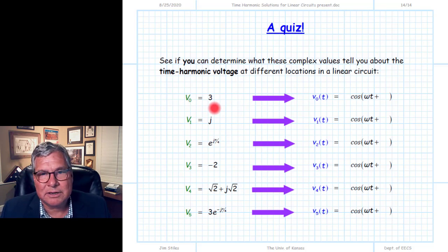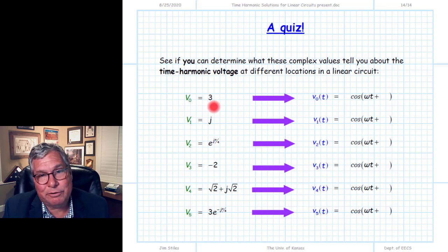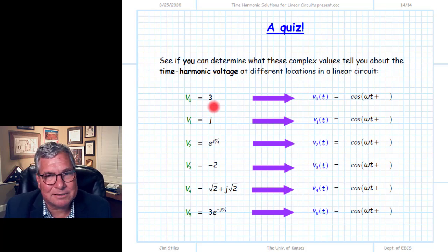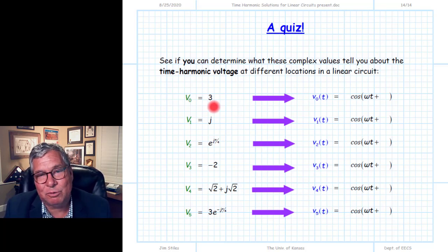And what I find in this course, and it frustrates me a great deal, is students over and over again decide that if I say the voltage is equal to 3, that we're talking about a DC voltage of 3 volts. It's just 3 volts sticking there at a time. In radio engineering, there are no DC voltages. They aren't very useful to us. Okay, sure, we have bias voltages for devices and such. But in terms of the circuit analysis, the high-frequency circuit analysis, all right, DC is not a high frequency. DC is a frequency of exactly 0. And we're talking about in this class frequencies that are going to be in the megahertz or the gigahertz in frequency, high frequency changing. There are no DC voltages that we'll talk about in this class for the most part.